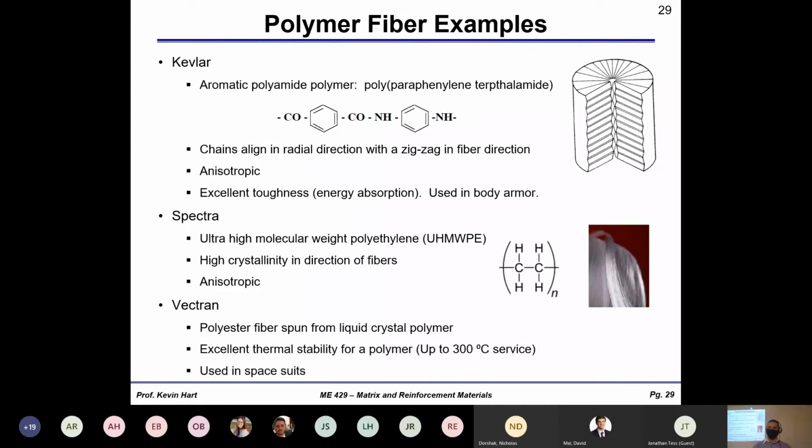So here's an example of Kevlar fiber and its particular structure. And again, the benefit of these polymer fibers is they're very tough, and so they have a lot of ability to expand that carbon fibers and glass fibers don't. That's why Kevlar is commonly used in body armor. If I shoot you, bang, bang, and you're wearing Kevlar, well, that polymer fiber, which is the backbone of that body armor, can absorb the energy associated with that bullet because you have very high toughness of these particular fibers. That's why Kevlar is commonly used as a backbone for the composite that is usually in body armor in general.